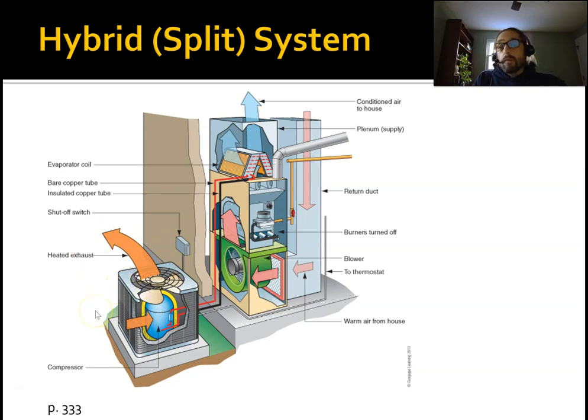air. So remember, going back to heat versus temperature, everything has heat. A block of ice has heat in it. It's a little harder to get that heat out the colder it is. And so the outdoor air, this is when I'm in heating mode, I'm actually pulling heat from outside here, right? That's through the evaporator. And then I take that heat and I dump it back in here through the condenser, and I go back out. I pull heat from outside, I dump it inside, pull heat, and so on. Okay, so that's air source heat pump. I'm taking heat from the air.